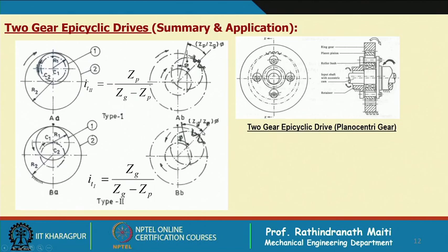Anyway, with this type of gearing arrangement with involute-like teeth, not exactly involute, with very small difference of teeth, because it will be advantageous only if we keep this difference very small, we have a gearing arrangement which is called planocentric drive, where this planet carrier is somewhat not the normal; it allows this gear to rotate like this with a hole.